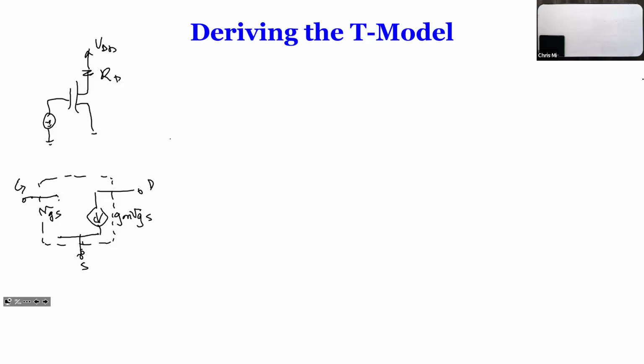So this pi model is perfect, as we said, for a MOSFET in the common source amplifier. But as I said, if you have something, let's say in the emitter or in the source, you will be having trouble, because all of a sudden your VGS is no longer the input, because your VGS is the difference between the input and the voltage at the source.